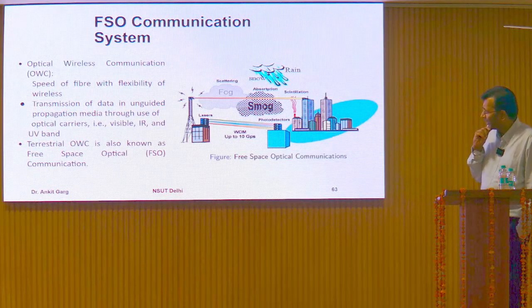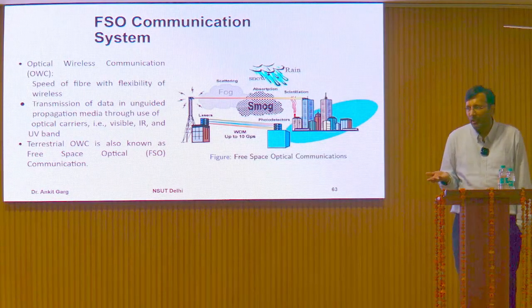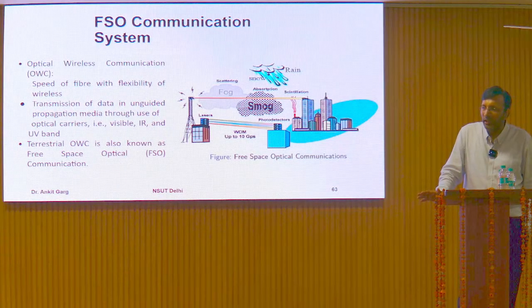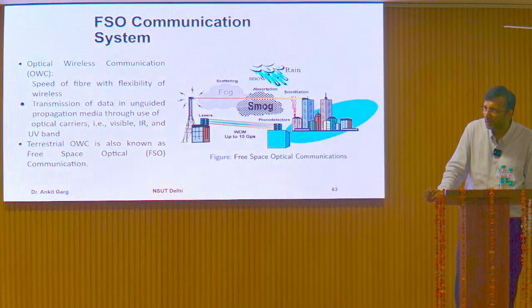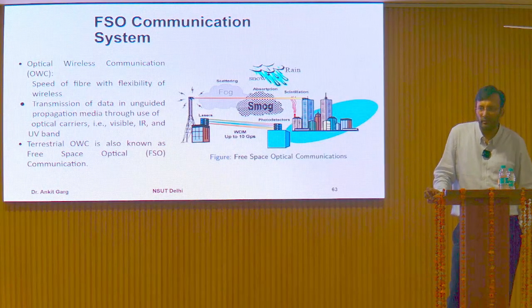It works upon line of sight. You can call it more secure, and the trade-off is that it's quite directional. We can't do anything multi-directional with this laser, which means broadcasting can't be done, right? And since it works with laser light communication, it has severe fading conditions like atmospheric turbulence, right? Eddies, that is the main word here.